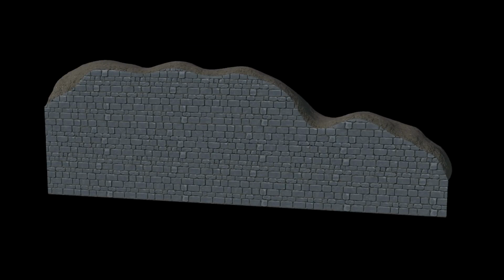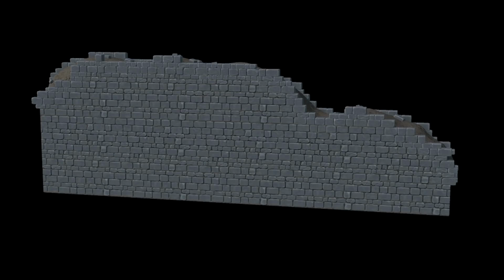And then once we cut it up, I isolate all of the seam points where the cut was actually made. And then I basically have all of the bricks lined up to match the UVs on the geometry where it was cut. And then it just puts all of the bricks in place that have been duplicated across the mesh. And then you end up with the artist never having to place bricks again.